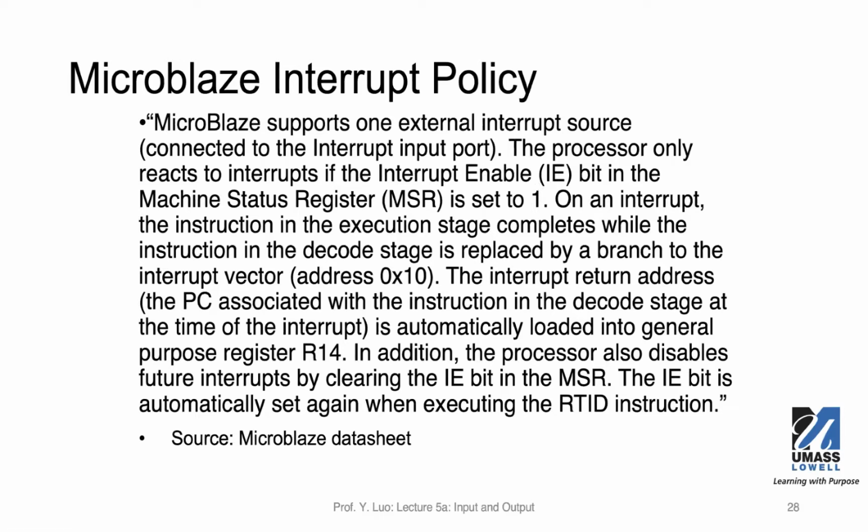If you set this to 1, the interrupt is going to turn on, so the microprocessor will be able to respond. It doesn't mean that you currently have an interrupt pending. It just enables the interrupt function, so that your interrupt service routine is able to be triggered.